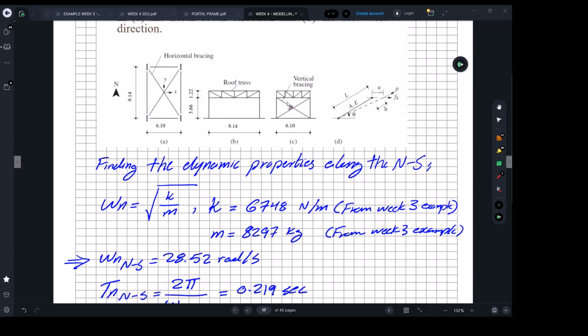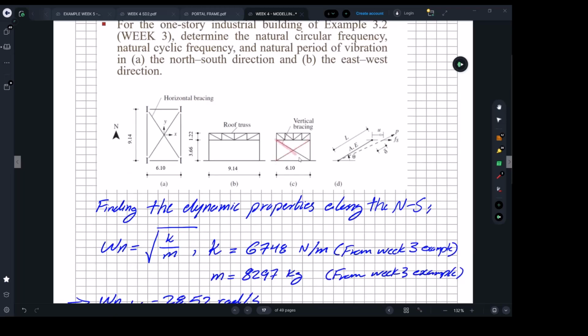Maybe you just need to add members like this. So what's happening without them? Let's say this was not there. The problem was resonance, which one of you already mentioned. If you have a car or a truck moving in front of your house and it's shaking the floor or making a lot of noise with a structure like this, the solution basically is just to stiffen it up a bit. When you stiffen it up, you change its natural frequency, and that's it. It's going to solve the problem.